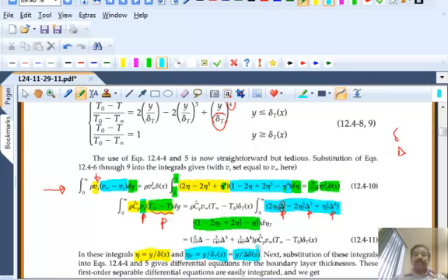Okay, why would you want to do that? Because you want the integration in terms of the thermal boundary layer thickness eta t. Okay, so the temperature profile is already in terms of eta T, but the momentum thickness is in terms of eta. So you need to convert that in terms of eta T. And that's what introduces this delta to the power 4, delta cube, etc.